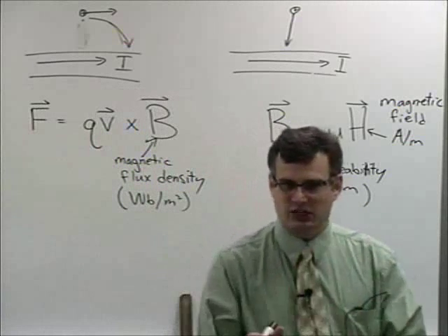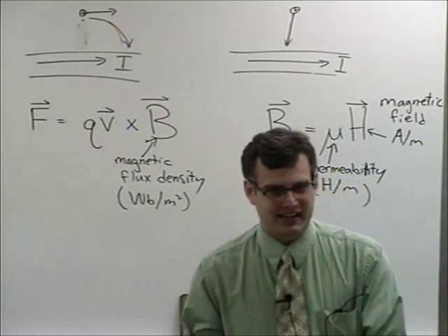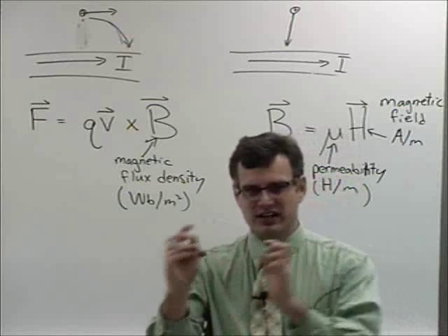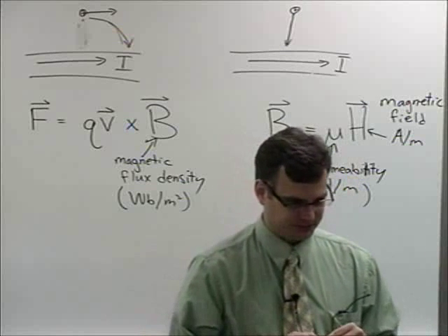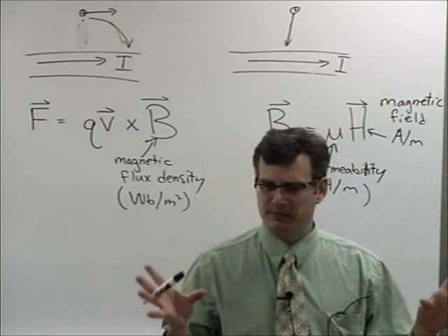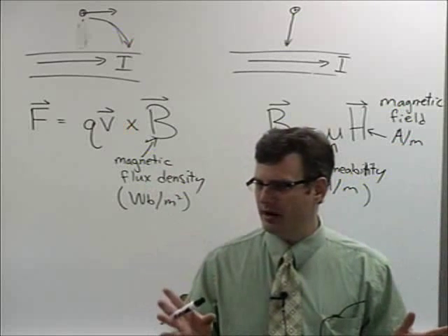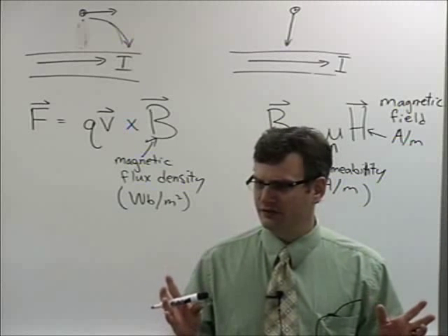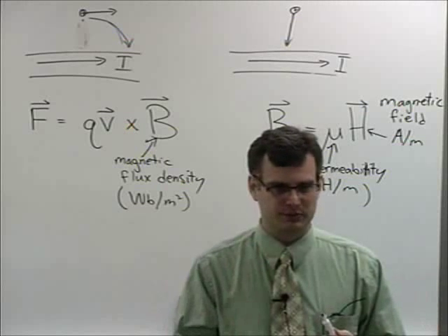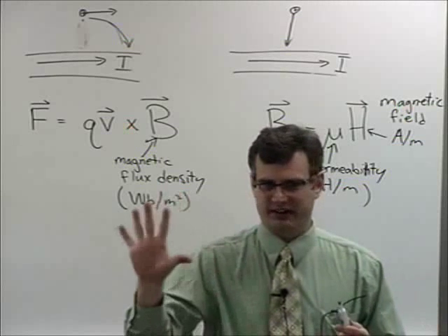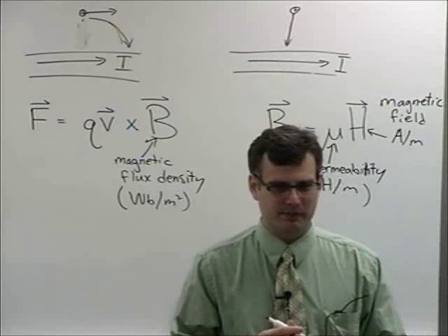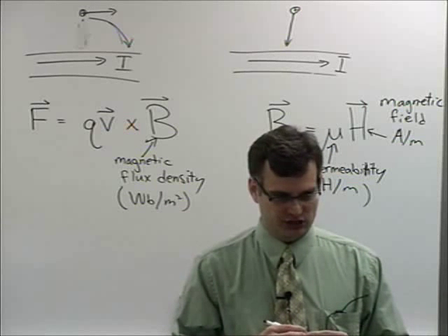You've got E and H, that's your electric field and your magnetic field. You've got B and D, your magnetic flux density vector and your electric flux density vector. There's a beautiful symmetry to solve problems. That way of setting up Maxwell's equations is particularly good for engineering problems, particularly those involving interfaces between junctions, like dielectric 1 and dielectric 2, because it's very useful for establishing and analyzing boundary conditions.